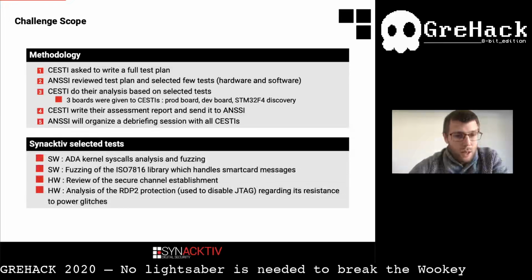In software, the analysis of the kernel syscalls with fuzzing and source code review techniques, and the fuzzing of the library used to communicate with the smart card. And in hardware, we had to do the review of the secure channel establishment with the smart card and the power glitch attack against the STM32 RDP protection that is used to disable the JTAG on the production boards.